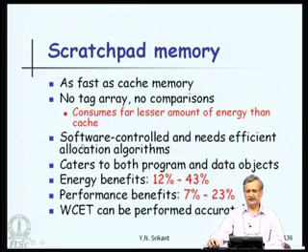Because they are very large, the scratch pads have to be software controlled and they need efficient allocation algorithms. It is not usually possible for the programmer to say I will use this part of scratch pad memory for this purpose and so on. Even though theoretically it is possible, it is better if the energy usage is all controlled by the compiler. So, it caters to both program and data objects, that is instructions and data both.